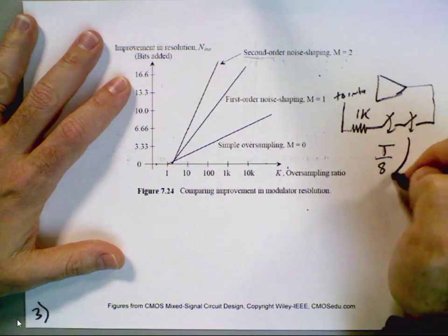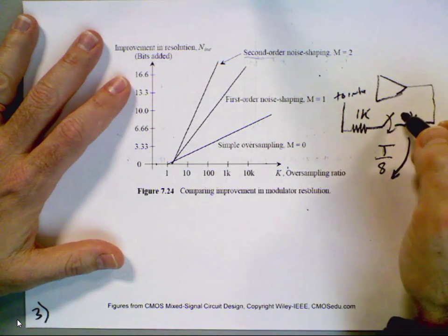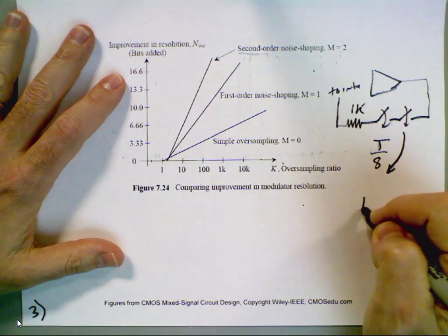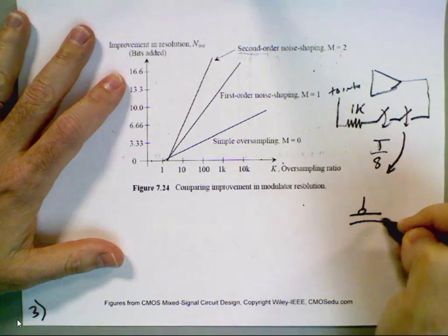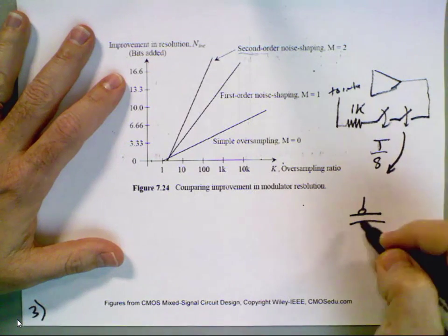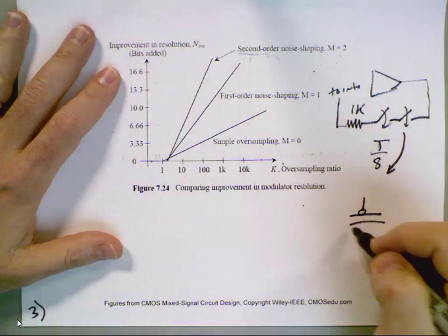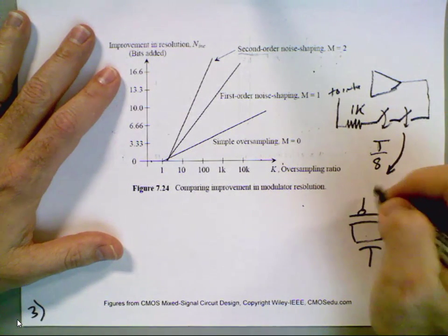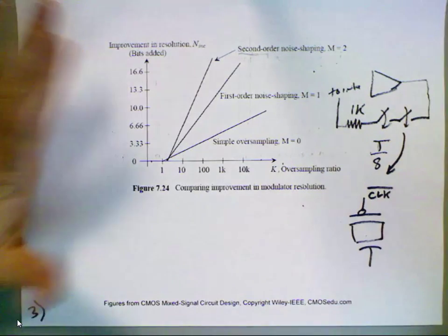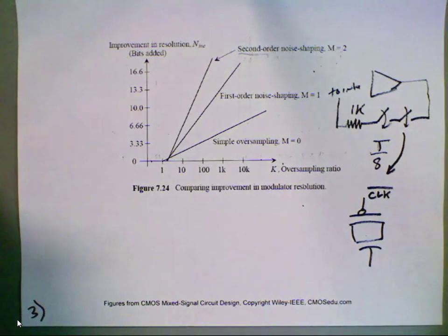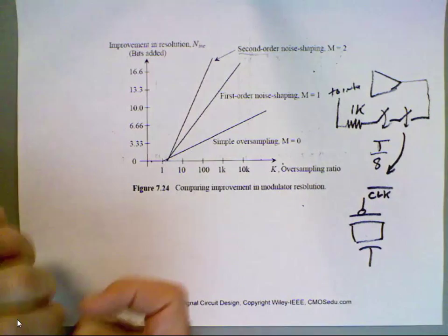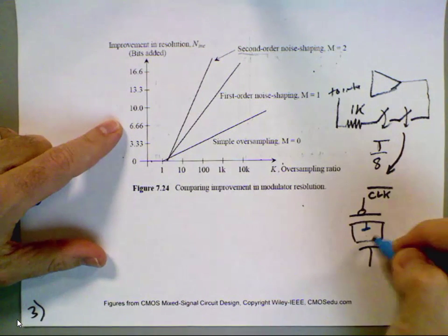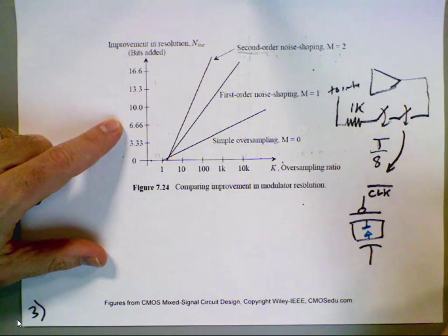What I'm getting at now is how do I implement those two switches? Okay, so what I want to do is something like this. Now, you might be able to do your design where you don't need these, but if you haven't taken the digital class, so this would be, to turn this on would be clock bar. So I'm not going to insult anybody here, but I want to make sure you follow. So when you put your PMOS, you've got to make sure that the body of the PMOS is connected to VDD and the body of the NMOS is connected to ground.